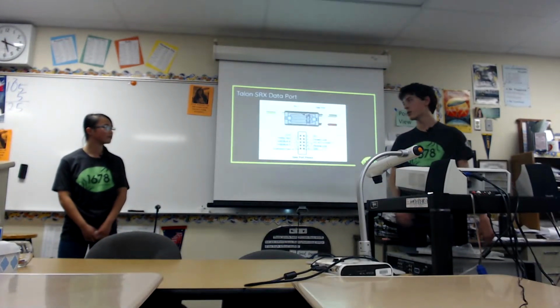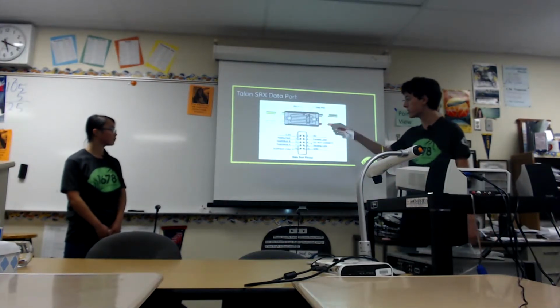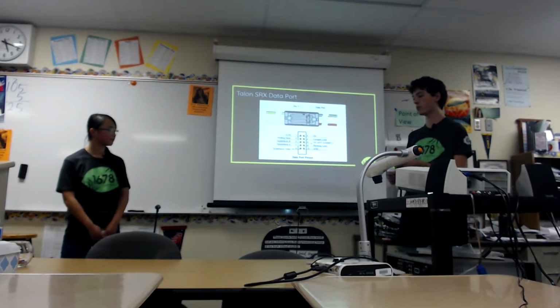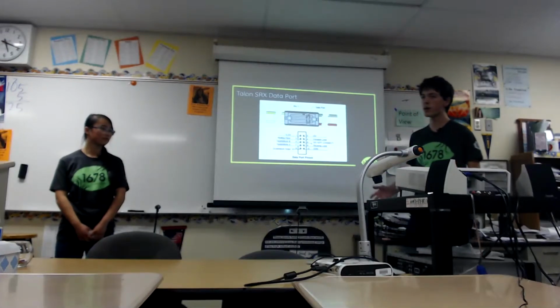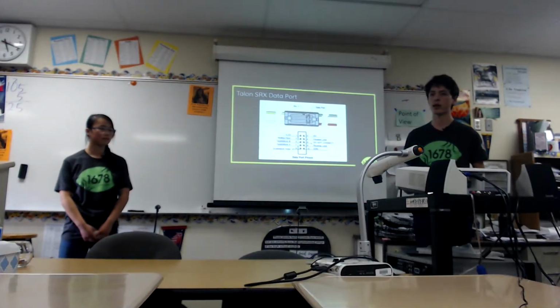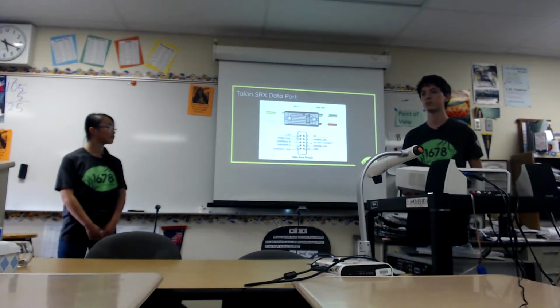Next slide. So the Pigeon IMU, as you saw on that previous slide, has a ribbon cable plugging into the Talon SRX data port. The Pigeon IMU uses a ribbon cable to connect to a Talon, it doesn't matter really which Talon, but it doesn't connect to the RoboRIO like other expansion boards like the NavX. It doesn't use the expansion port.